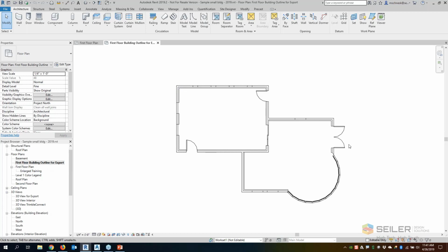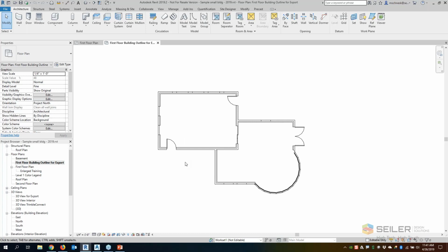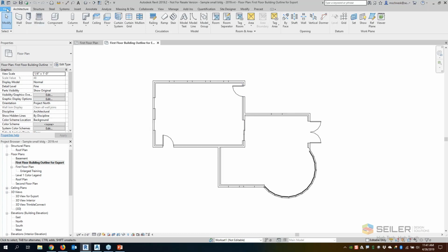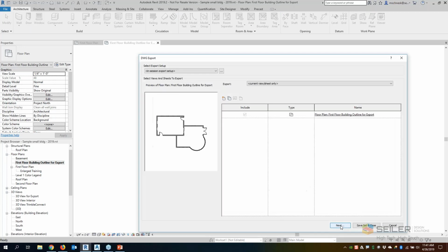But for the purposes of what I'm going to do for this, if I'm trying to share my building outline to the civil engineer so he can put it on the site and make his site grading to it, make sure that we have the right grading to the entrances and stuff, I would select my view, what I'm going to share. I'll come here and say File, and I'll export CAD DWG. So I'm going to export this out as a DWG model.